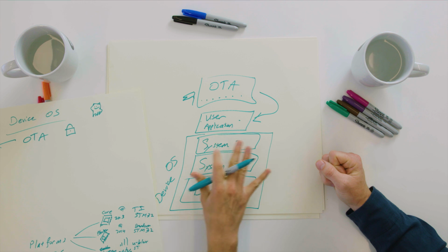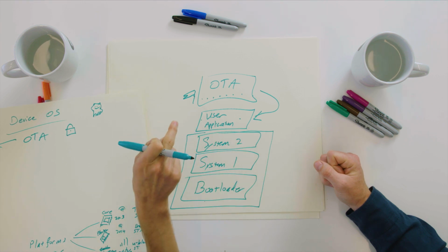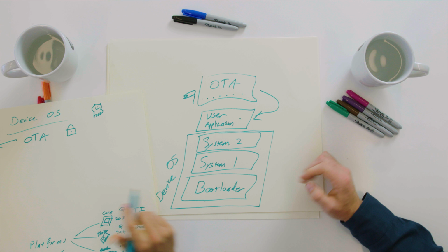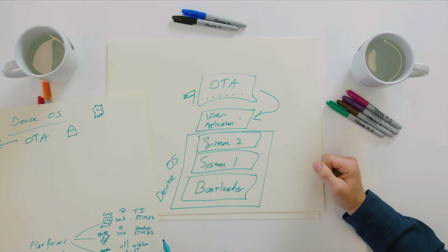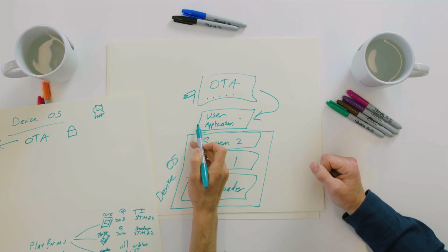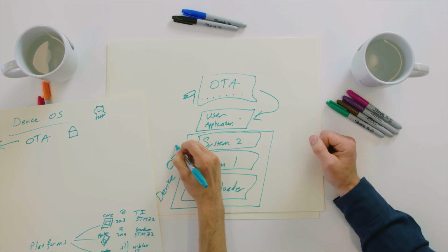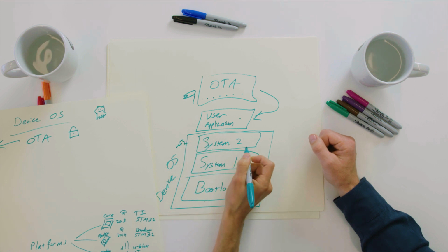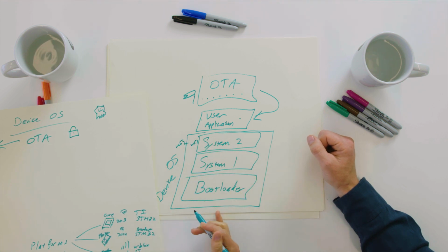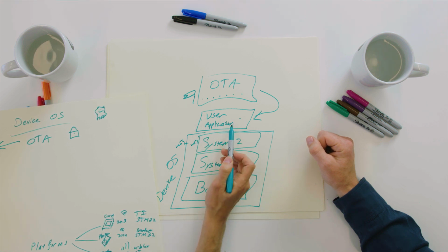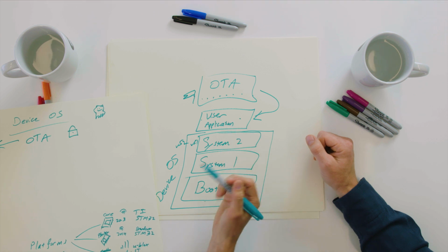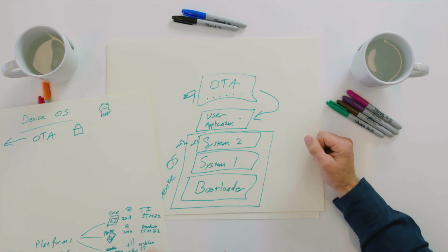Totally. The one caveat, to go back to something you said, you're like, oh, but you're not updating this. Yeah. If you build the user application for a new version of the device OS, there is a dependency chain where this has some metadata that says, I depend on device OS version 52 or whatever, and what you have here is 51. And so the system will see that, boot into safe mode, and not run this application because it assumes the dependencies aren't met. And the device service will start sending down automatically that new version through the same process.